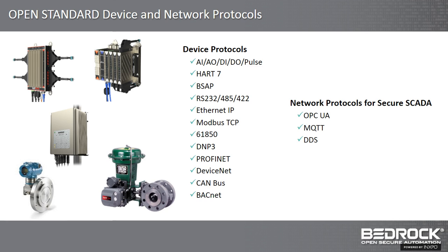There's too many smart ways to get these protocols and these devices into a gateway, into a client, into a device, a PLC that can immediately take that legacy protocol and convert it to a secure standard Ethernet. It exists, and these devices at the edge have to support any number of these protocols. It has to be there, so you don't have to try to buy one device versus the other. Good digital technology, good design will ensure that an appliance, a device, a PLC, some modern device can interconnect and bring these legacy buses to a modern bus architecture that can be accessible to the Internet.